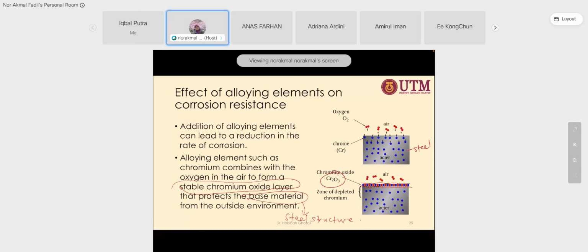it will quickly form an oxide. So there's no chance that iron will form oxide. Inside you have iron also. Without this, iron will form oxide, which is an orange-like structure that you see as rust. Correct. Iron oxide is rust. But if you add chromium, chromium will react with oxygen faster, because in the series of electronegativity, it will easily react with the oxygen. It will react faster. There's no chance that iron will react with oxygen.